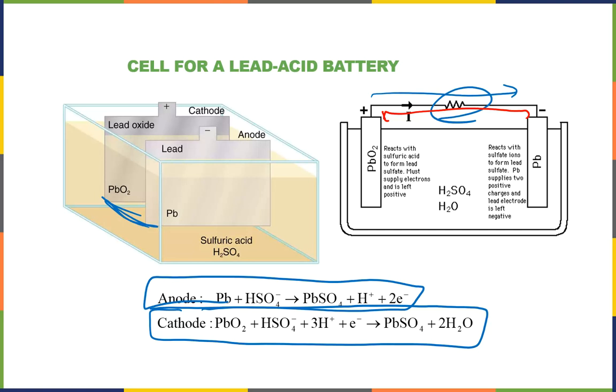So how you test a battery, you don't test it by measuring the terminal voltage of an unused battery, because the terminal voltage should always be the same unless it's completely broken. But if you put a load on it, if the chemical reaction can't go quickly, the voltage drops a lot. That's a bad battery. And so when you put a load on it, you measure how much the voltage drops. That tells you about the battery state. So battery testers are always going to put a load on the battery and measure how much the voltage drops when you put a load on it.